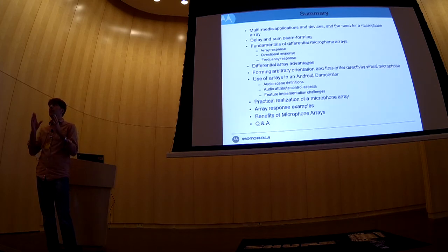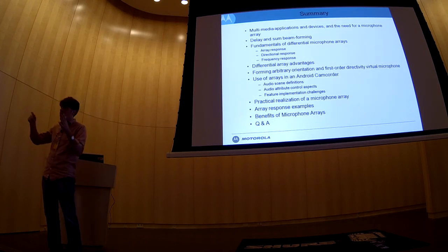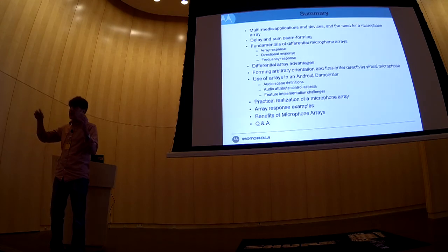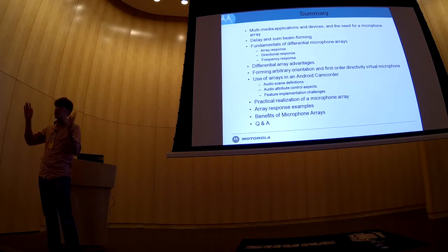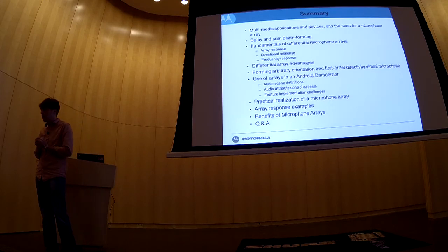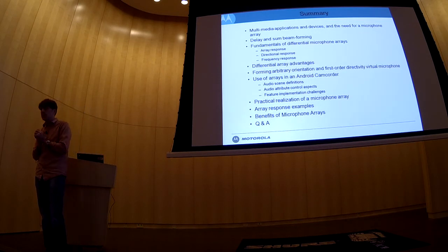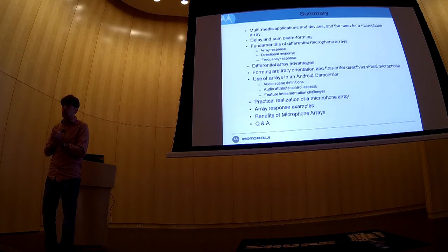I think I wanted to mention that in itself becomes a challenge. Why? Because the microphone comes in from the manufacturer and they have some resonance, let's say 17 kilohertz or 20 kilohertz, depending on the actual mic. And so when that is ported, that resonance becomes lower, much lower.